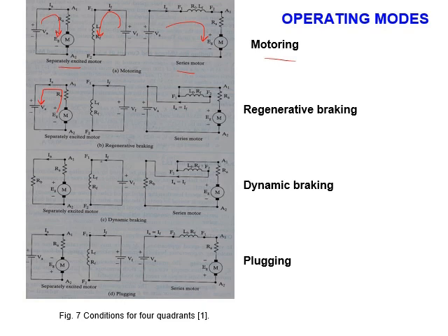So the motor here works as a generator, generating back. You may ask, why do we use this for braking? Braking has applications. In industry, we need movement and we need to stop in some places, so braking needs to be done. Braking is either electrical or mechanical. With mechanical, we have friction and many problems, and it's not as smooth as electrical. Electrical is softer, smoother, flexible, and very accurate to control. So for that, they use regenerative braking.